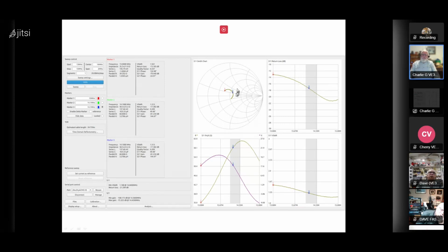If we take a look at the Smith chart here, you can see that the antenna seems to be more reactive rather than coming in here, bang on at 1 with no J component at all. Well, it now does have a bit of a J component. In fact, what I measure is 58.3 ohms resistive and 12.2 ohms reactive, rather than the milliohms I had before.